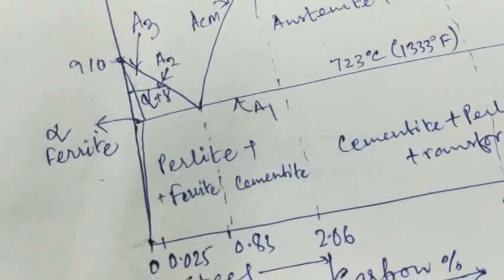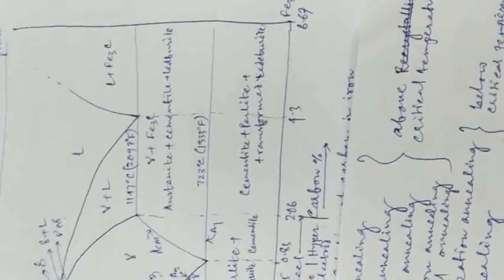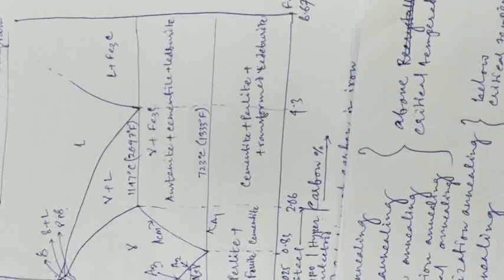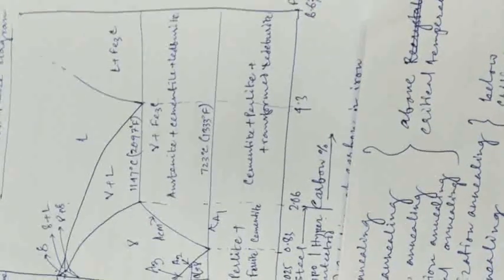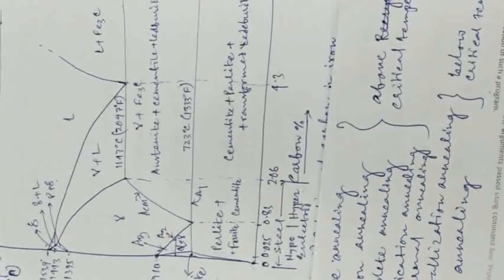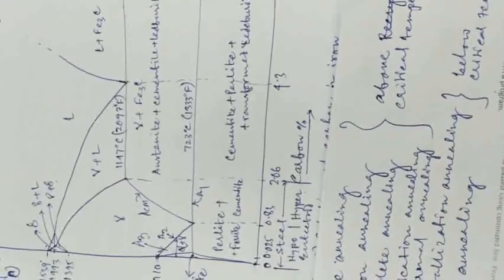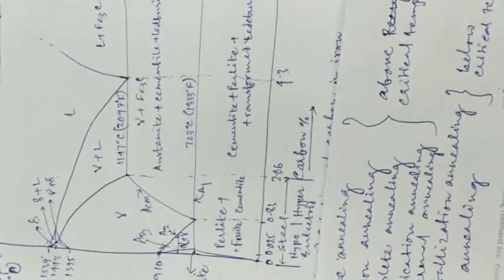How to choose the annealing method. First of all, the various steels of hypoeutectoid structure generally select complete annealing. In order to shorten the annealing time, isothermal annealing can be used. Spheroidizing annealing is generally used for hypereutectoid steel. When the requirement is not high, you can choose not to do complete annealing. Tool steel and bearing steel often use spheroidizing annealing.